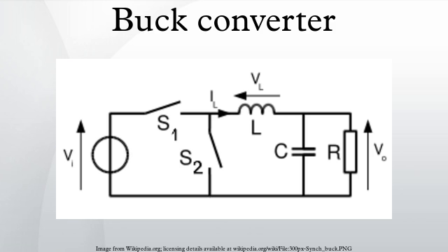The primary advantage of this type of converter is that it can respond to load changes as quickly as if it switched at N times as fast, without the increase in switching losses that would cause. Thus, it can respond to rapidly changing loads, such as modern microprocessors.